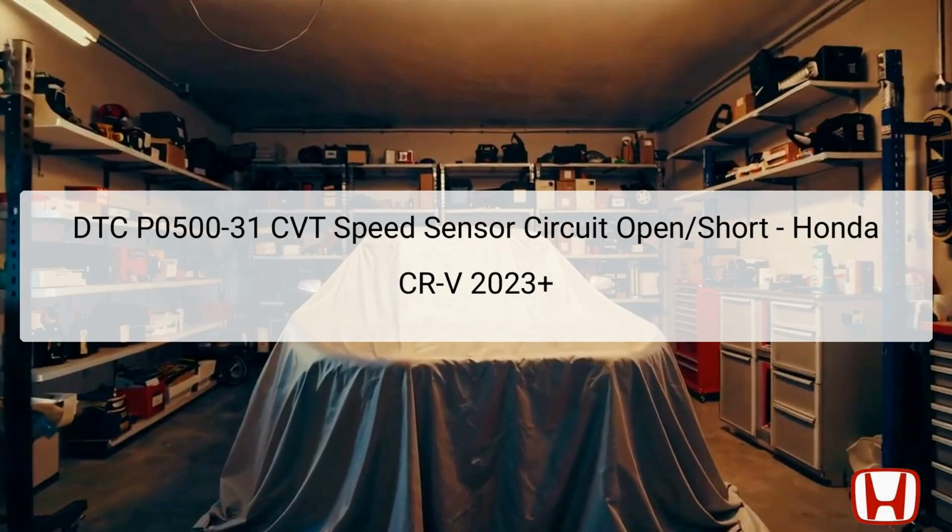The CVT speed sensor is crucial for determining the vehicle's speed, as it provides input to the TCM for optimal engine performance and transmission management. This component is typically located on the transmission itself. A failure here can result in erratic shifting behavior and reduced vehicle performance.